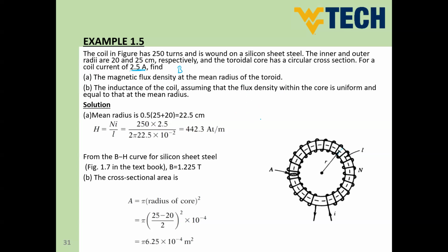In order to get B, again, let's write down the relation, Ampere's law, MMF, Ni equals phi times reluctance equals H times L. Whatever term you need to use, you can use according to the data you have here. So we need to get B, and we can get B by means of phi and the cross-section area, or H and permeability.